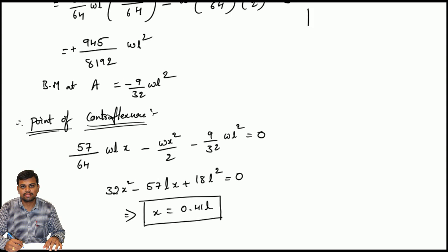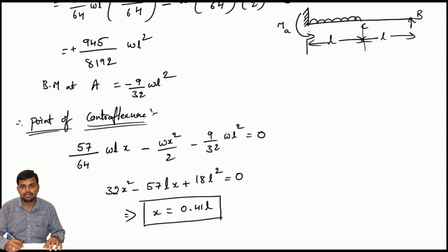Here what I am doing is I am drawing the beam. This is a UDL up to the point C, and it is L, and this distance is L. Here you have a vertical reaction at the end B, and here a moment MA and a vertical reaction VA, and this end is A. So for this I am writing out the shear force and bending moment diagrams.